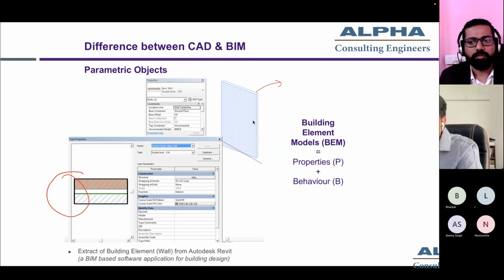It's not just a material wall in general. With the documentation of a wall, with the insertion of a wall inside a digital model, we have some expectation in terms of properties and behaviors. So the properties inside it, let's say thermal properties, analytical properties or strength related parameters, these are also part of the basic BIM workflows. So you can have the calculation of U values with the wall assemblies you are creating inside these BIM softwares.